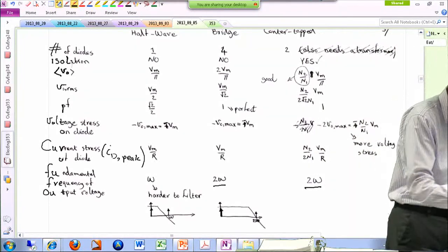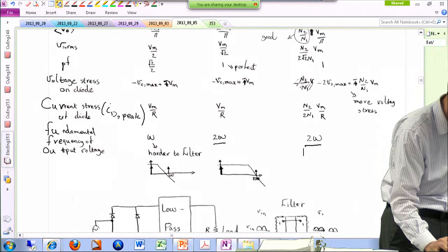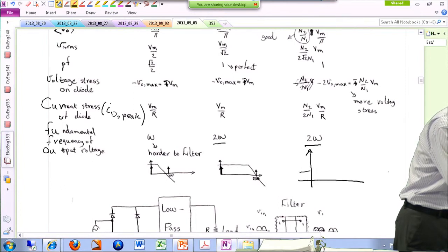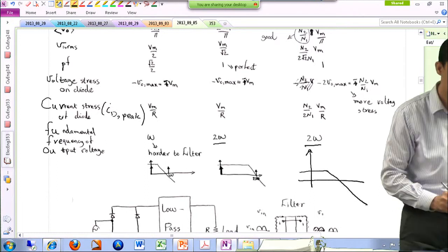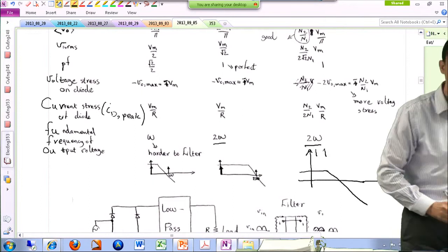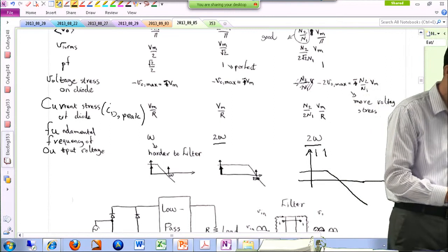So basically what I'm saying is, if you look at the Bode plot, or the magnitude of the transfer function of your low-pass filter, let's say it has something like this. On this axis we have frequency, and on this axis we have the magnitude of the harmonics, or this is actually the magnitude of your gain.